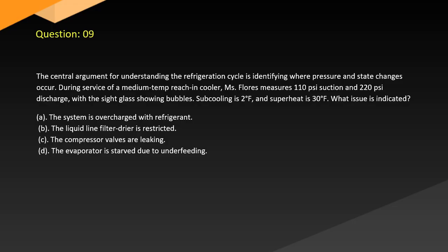A. The system is overcharged with refrigerant. B. The liquid line filter dryer is restricted. C. The compressor valves are leaking. D. The evaporator is starved due to underfeeding.